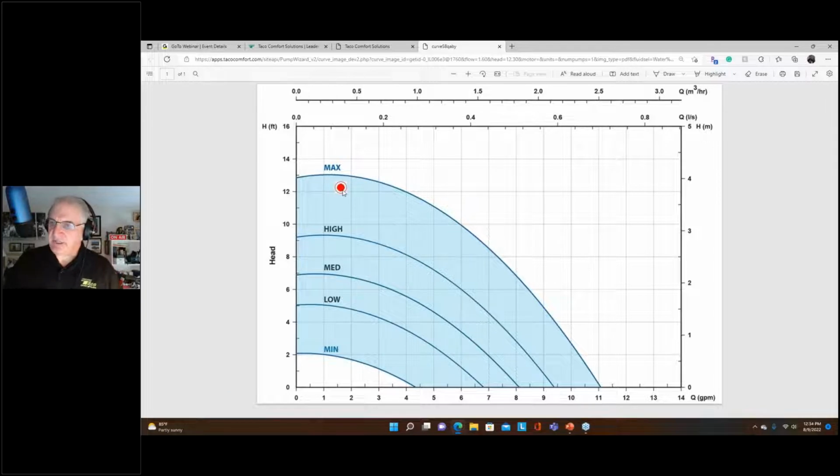Now, the 006E3 has a dial, kind of a smooth volume dial. The more I turn it up, the faster it goes. So from the looks of this, I would set that dial at just a shade below the max setting. And now I would have the flow rate I need, the velocity I'm looking for, and effective recirculation.